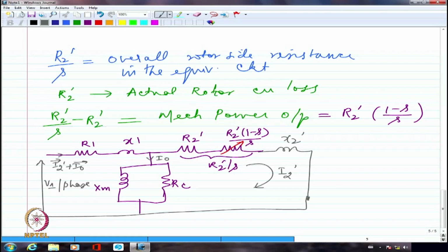And the rotor is carrying a current which is producing the torque, but that current is also coming from the stator. It is like a transformer. So the stator current will contain the magnetizing current as well as the torque producing component of rotor current. Both will be there.